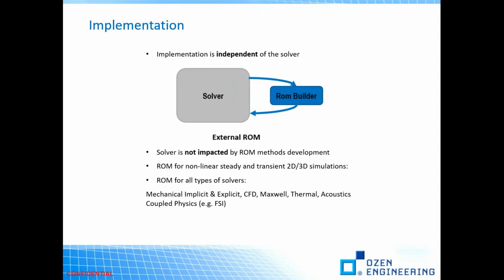The solver is not impacted by the ROM method's development. The ROM works for nonlinear steady and transient 2D and 3D simulations, and our ROMs are available for all the solvers: the physics of ANSYS mechanical implicit, explicit, CFD, Maxwell, thermal, acoustics, or even coupled physics, for example fluid structure interaction.